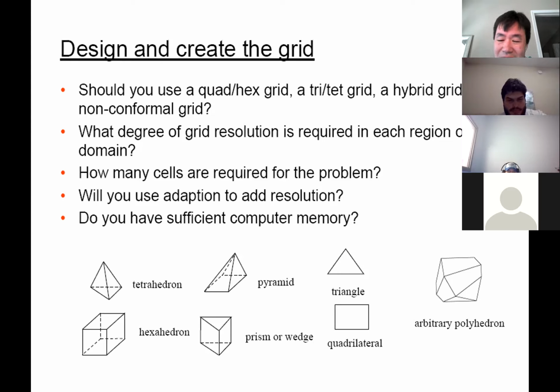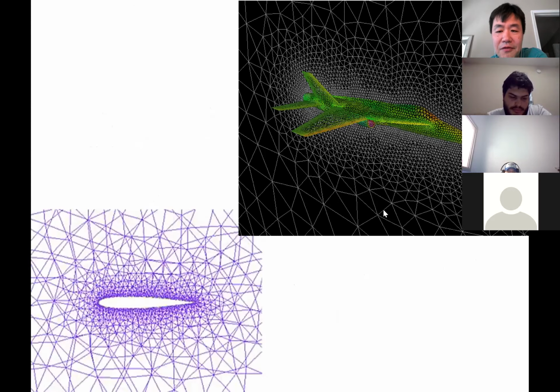That's why in the early days, when we didn't have this software and developed our own code, we really needed to be careful. We had to play with all those mesh grid shapes to make a good one. So it's not easy. Now Fluent and ANSYS Workbench do it for you, but sometimes it still comes out with a bad mesh. It's really possible. The rule of thumb is the mesh has to be finer.